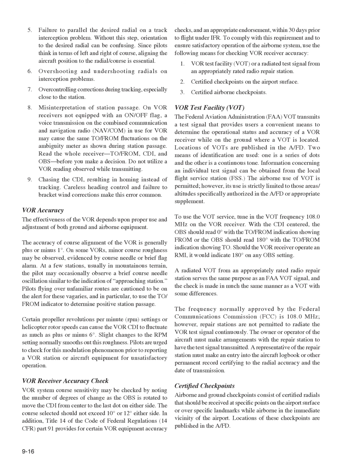Certified checkpoints. Airborne and ground checkpoints consist of certified radials that should be received at specific points on the airport surface or over specific landmarks while airborne in the immediate vicinity of the airport. Locations of these checkpoints are published in the A/FD.